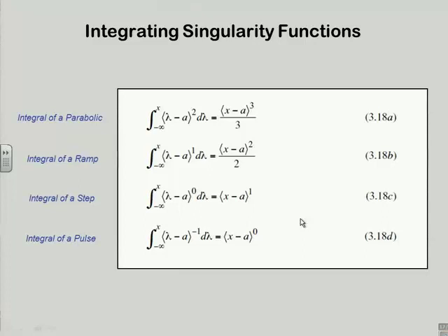So I start by writing the Q equation with the appropriate collection of these things for pulses and uniform things, and then I integrate using these expressions to get the other four equations: v, moment, slope, and y from the Q. There's 5 to start with.